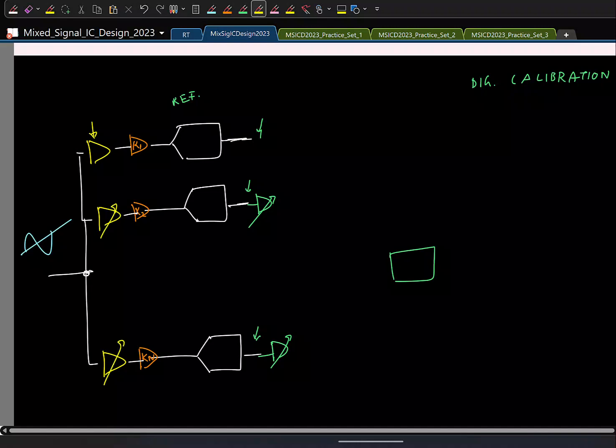In some applications you need an amplifier before the ADC to amplify the signal before digitizing. In that case, you can program the gain of this amplifier. Either of them will do.